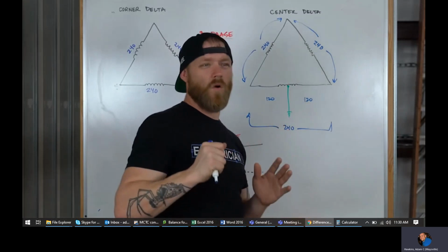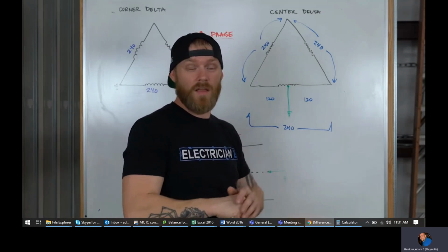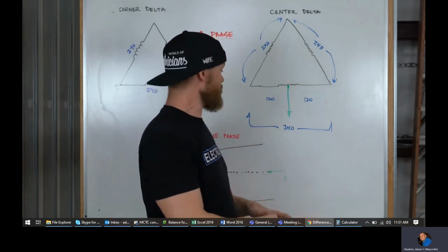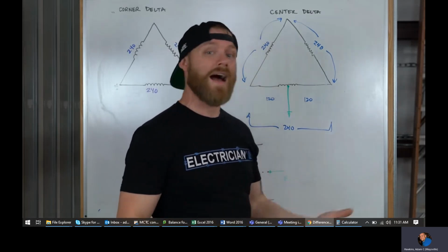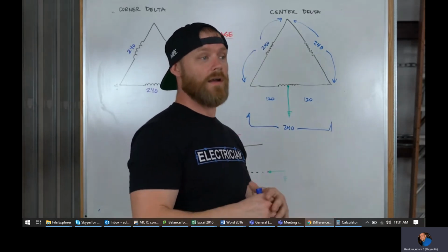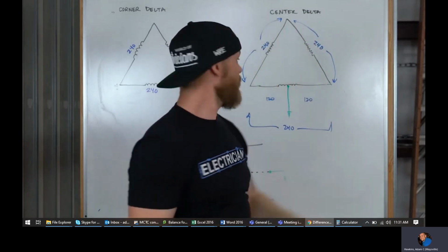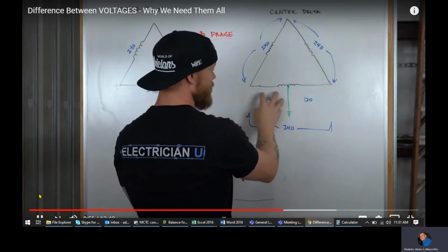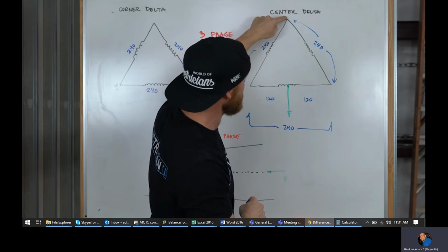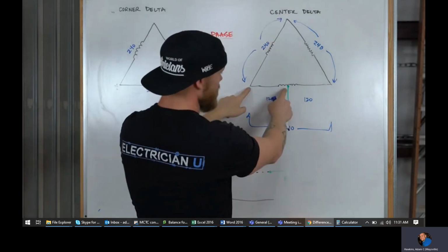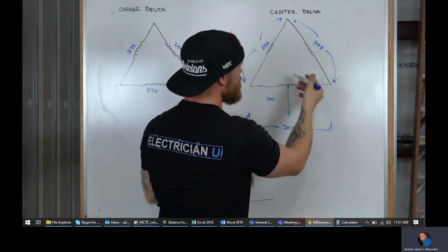A lot of older buildings, even houses, like there's places around here in Austin, old lake houses, that we come across have this three-phase 4-wire system where it has what we call a high leg or a wild leg, and it's usually one of the incoming wires coming up from the transformer. It has orange tape around it, and the reason is we have standard voltages everywhere in this system, but look what happens when we try to take voltage between this and ground. From here to ground we get 120, here to ground we get 120, but from here to ground you get 208,